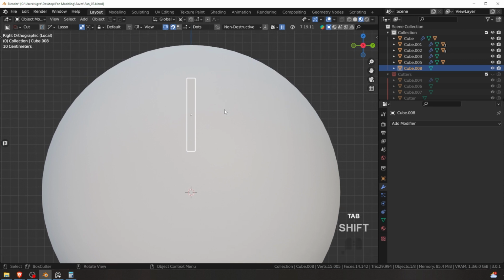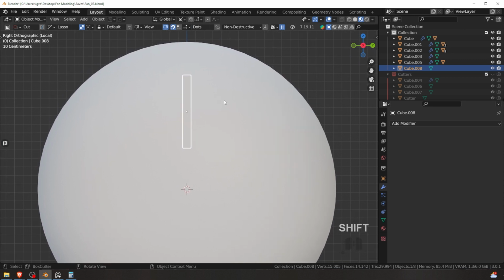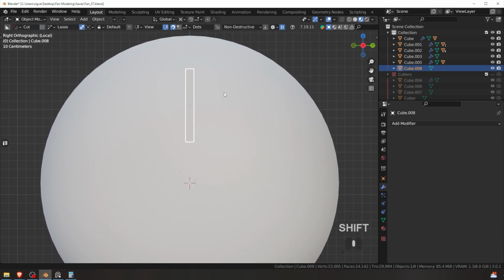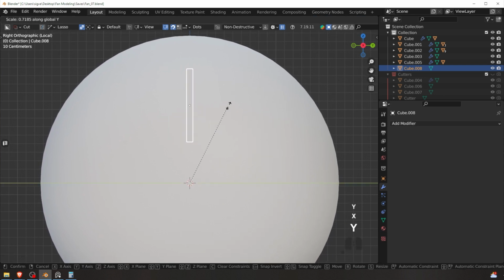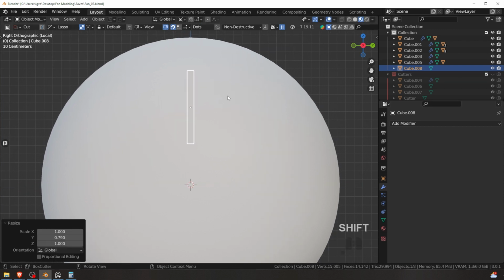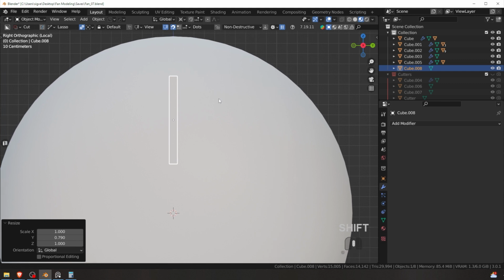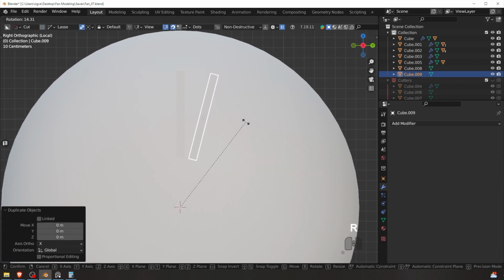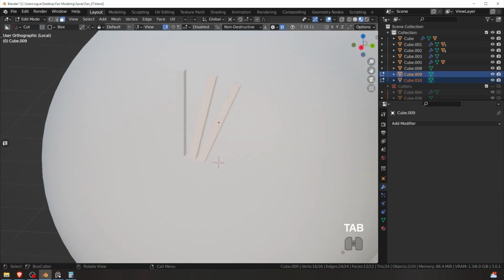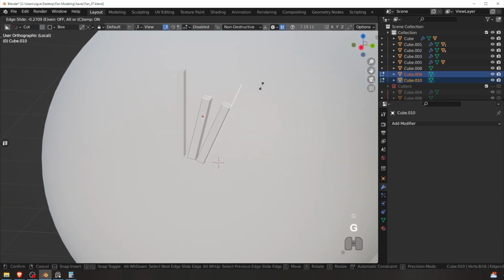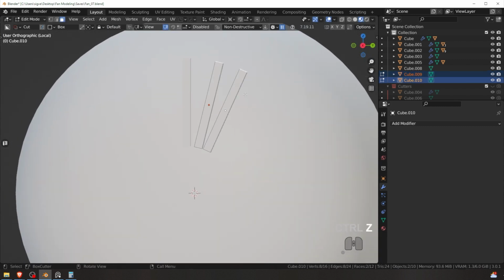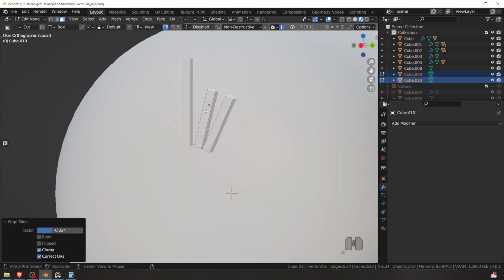So right now I'm going to show you what happens if you do it normally, and then I'll show you what happens if you make it too wide, this thing. So here, like that, and then just Shift D, rotate it a little bit, and Shift D, rotate it a little bit again. I'll select these two, go into edit mode, select these faces, press GG twice quickly, and just reduce its size. Like that. Maybe it's an overkill. It has to be something like that.